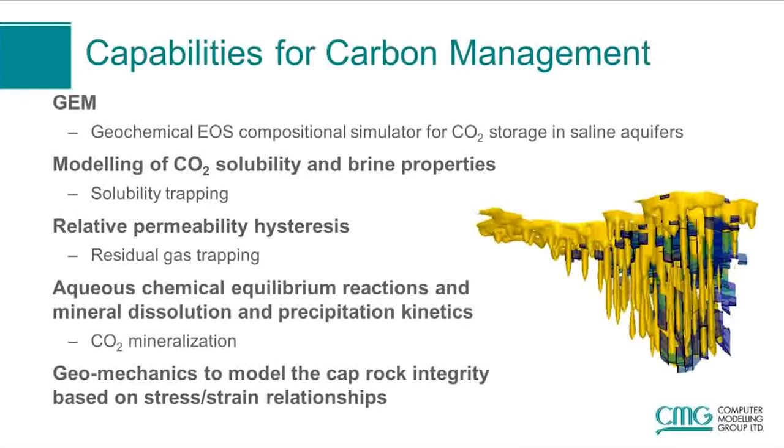The solubility trapping can be captured with the modeling of the carbon dioxide solubility in the water phase and the change in the properties of the brine. The residual gas trapping or hydrodynamic trapping can be captured with the relative permeability hysteresis. The carbon dioxide mineralization can be captured with the aqueous chemical equilibrium reactions and the mineral dissolution and precipitation kinetics in GEM.